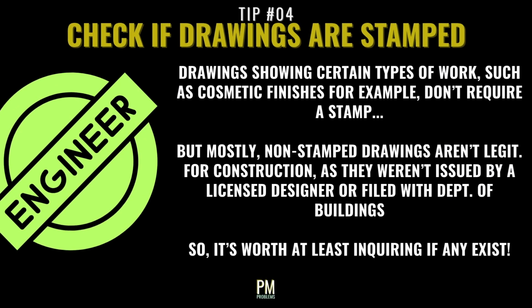Another tip I have is to make sure the drawings you're looking at are stamped. I have to give the disclaimer that this isn't always the case. For instance, if a drawing is depicting carpeting and paint, it doesn't require an architectural or engineering stamp. But the general rule of thumb is that if drawings aren't stamped, they're not legitimate for construction, for all intents and purposes. That's because any drawings that are deemed legitimate for construction have been filed with the Department of Buildings and permitted for use. So generally speaking, it's worth at least inquiring if there is a set of stamped drawings available before you ever begin any work.